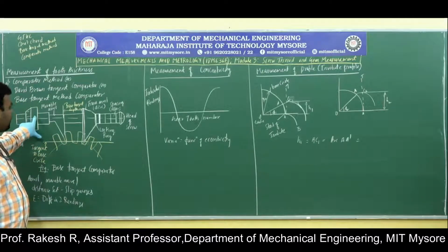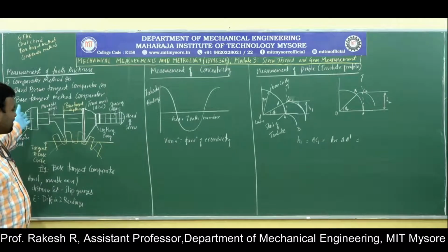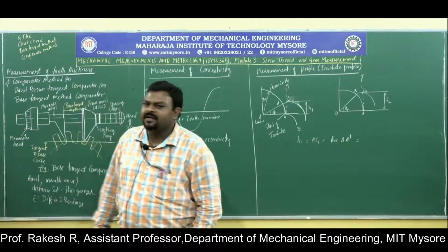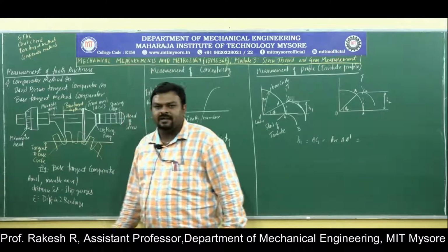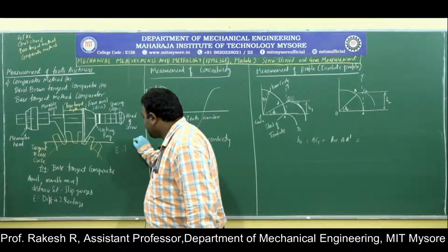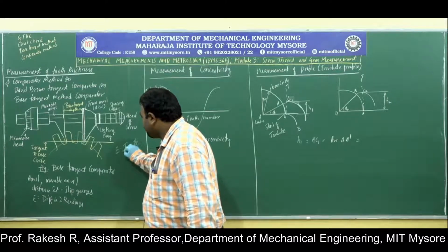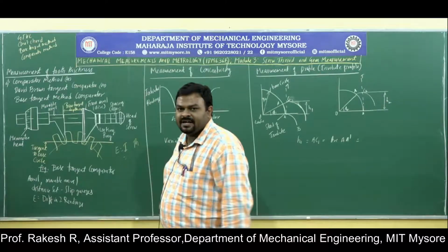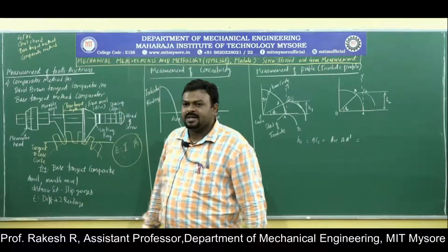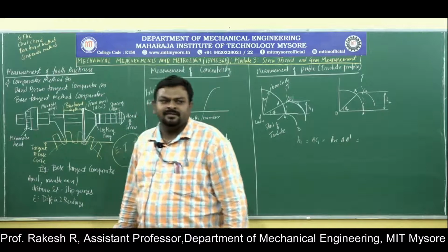Also the micrometer head will show the reading. For that you will do the corresponding calculations. Basically you will be calculating error. Error is instrument value minus theoretical value. Instrument value you will get something, theoretical value you will get something. This deviation will give you the error.